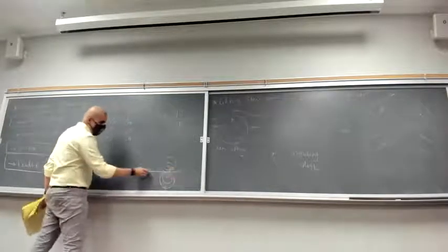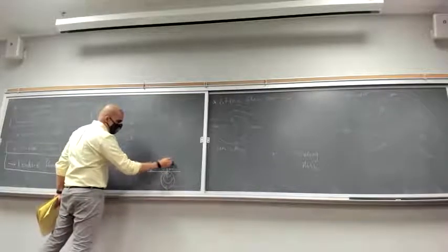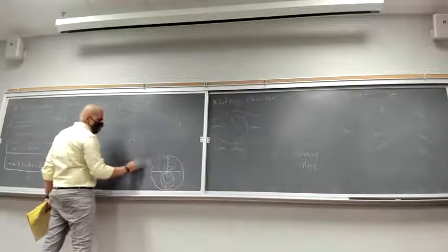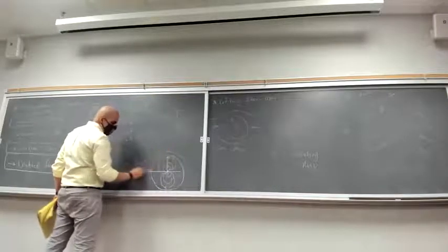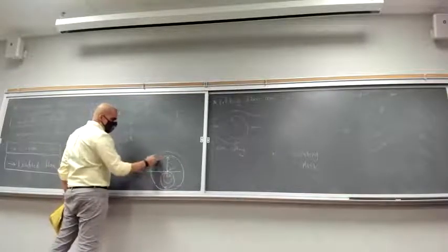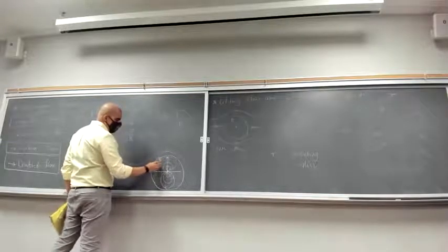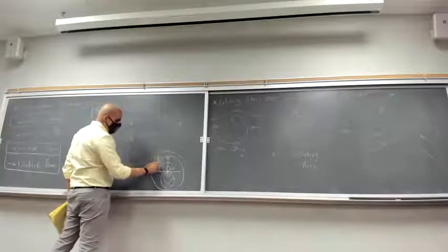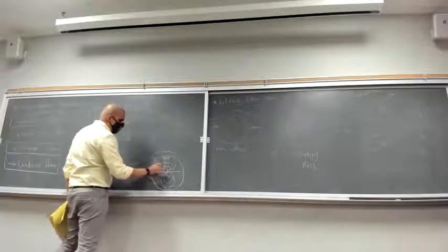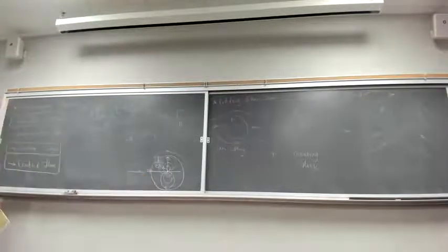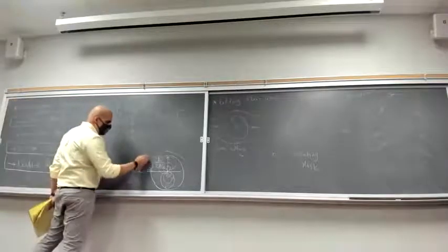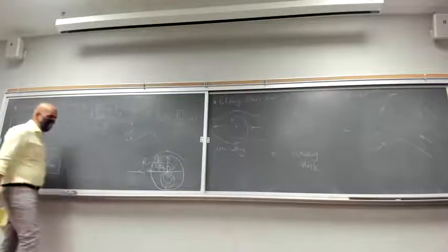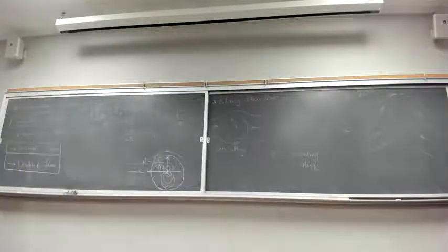This length here from the center, which is essentially, in your flow over the cylinder, going to be the radius, is equal to kappa over 2 pi v infinity. We can show that, but just accept it. So r is equal to the square root of kappa over 2 pi v infinity.